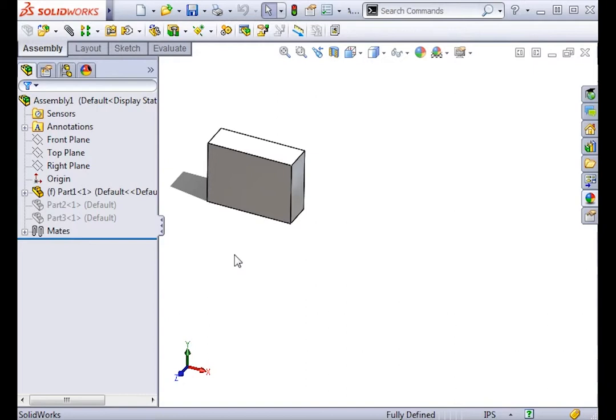Of course, since I'm thoroughly familiar with what I've done in this example, I can simply click Browse when opening the assembly to find the correct files and essentially repair the broken pointers. I can even change the Part 1 pointer to look at the correct modified file.